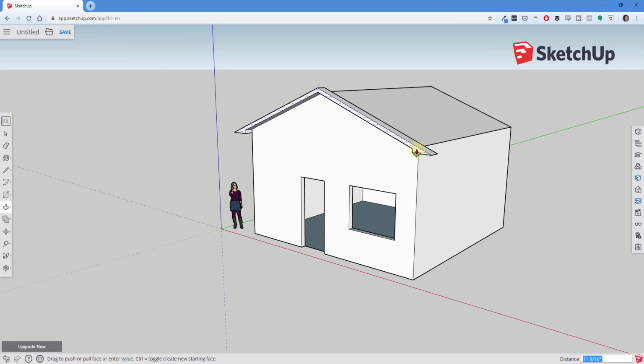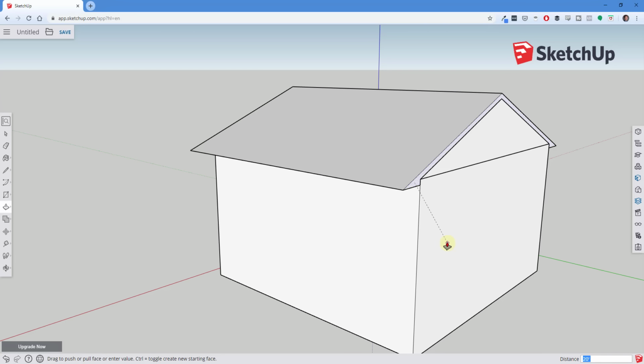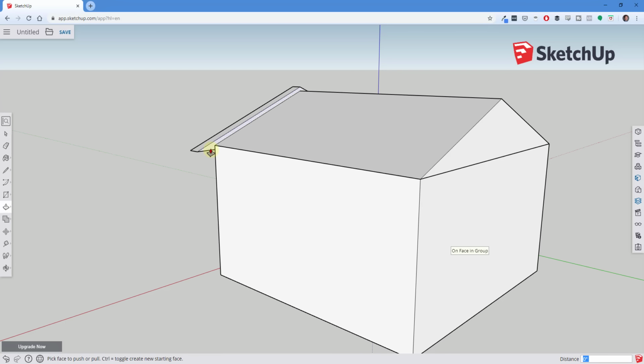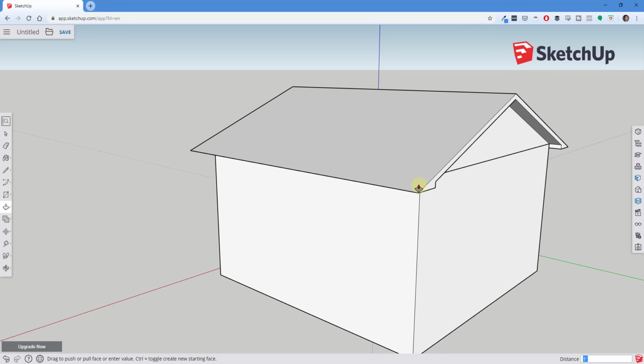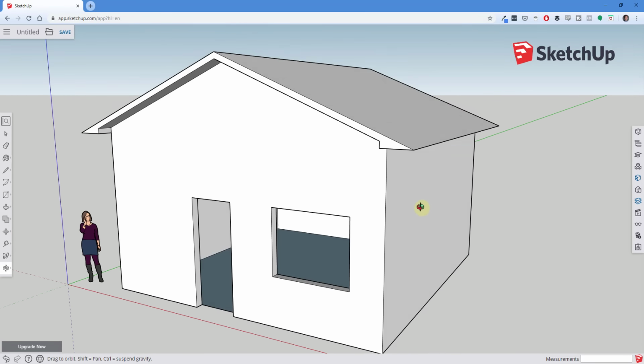Then we're going to use the push-pull tool, single click on this, move my mouse forward, and type in a value of 12 inches. Then I'm going to orbit around using my middle mouse button and push-pull this back until it's level with this back wall. So push-pull tool, tap the P key, single click, and click on this back wall somewhere. Then we click again and push-pull this another 6 inches or so, or 12 inches. Now that gives us this nice house model in here.